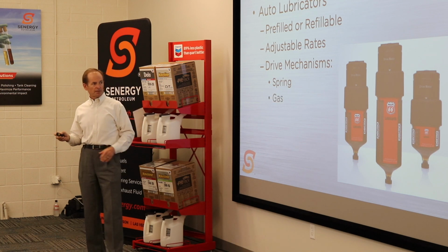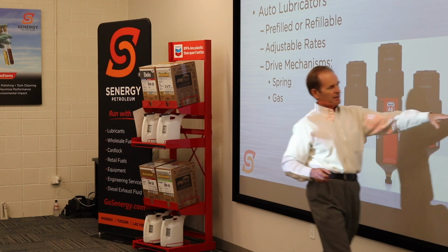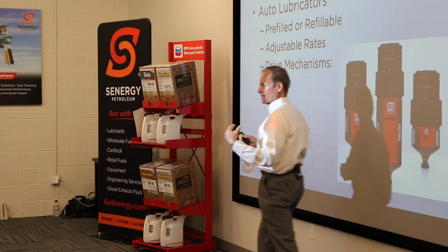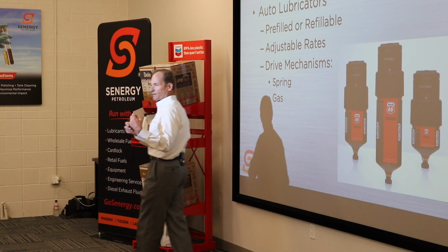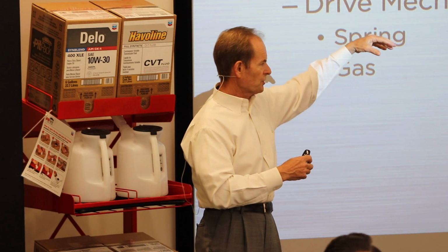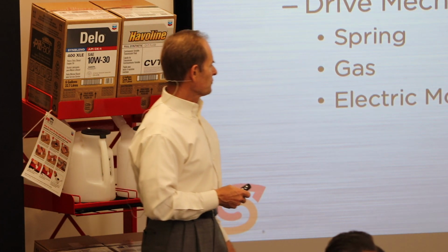There are also some, these two over here are actually gas-driven. There's a little button up here that's got a slow reaction going on, generating some sort of inert gas, which is pushing down on that grease and pushing it out. Less force than the spring. It pushes out just enough, lets the pressure build back up, and pushes out some more. Again, constant rate. And then the high-tech version are the electric motors.